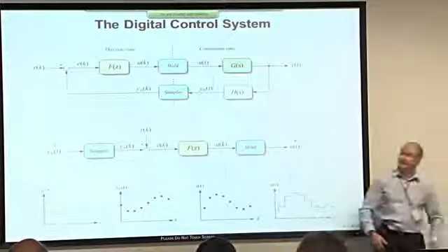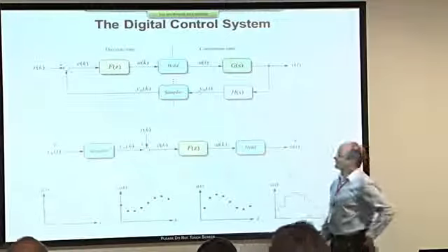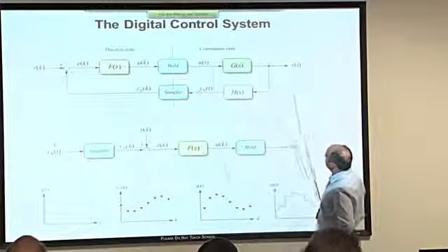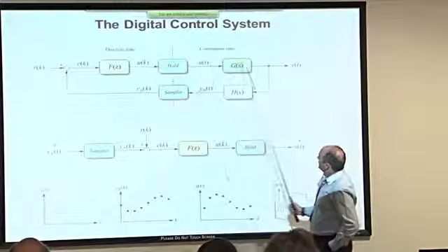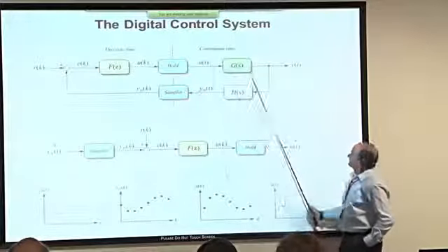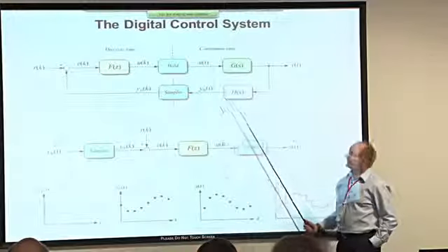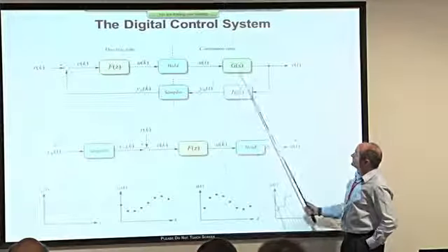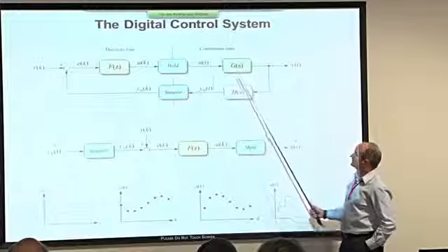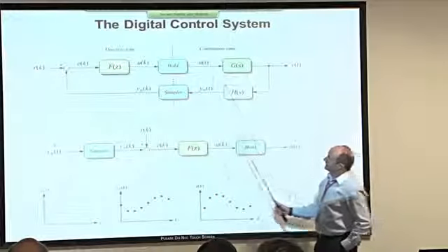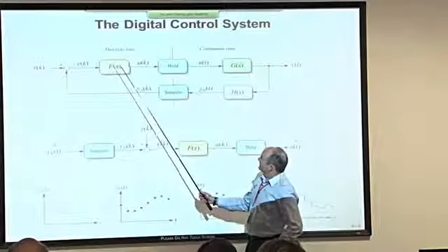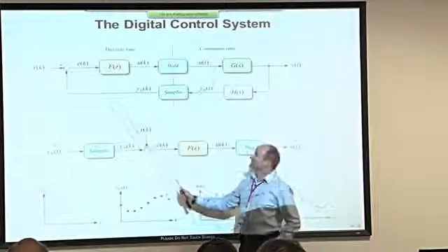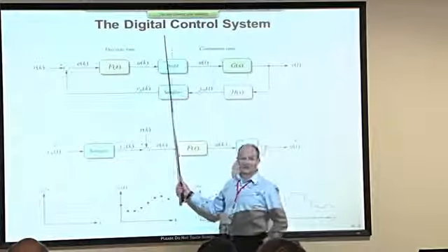The same kind of loop that we looked at in chapters 2 and 3. There is an output, a feedback, a summing junction, and a controller. And the plant and the sensor, well, I'm going to assume that these are still continuous time parts of the system. They still have a Laplace transform and transfer functions, but the controller exists in the discrete time part of the system. And there is a boundary between these two parts formed by, well, we can call them converters if we like.